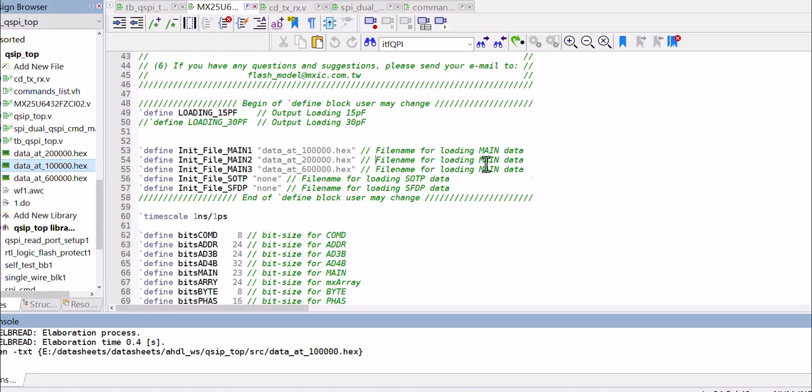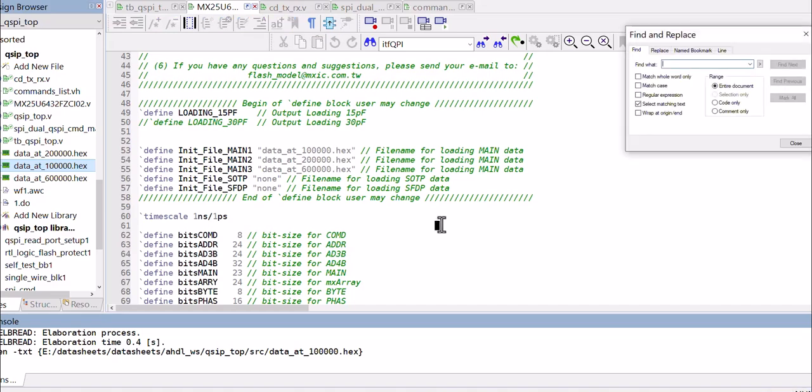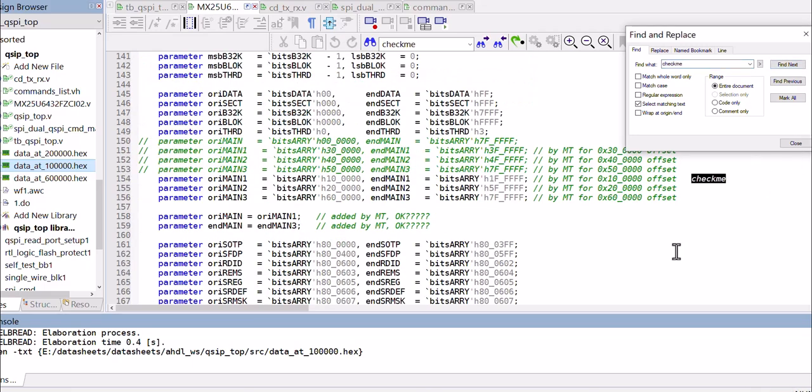So these are the manual edits we have to do for loading some specific code into this memory. Also there are some certain changes we have to make. We have to give the starting address where this data will be stored, so we have to specify the starting address and the end address of that file. So for 3 files here I provide the starting location and end locations.